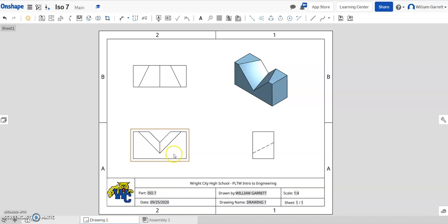So I could dimension a solid line on here. Like I could hit that bottom line, or I could hit this vertical line. If I want to, I can go point to point. I will point to line, so I'm going to start doing that. I clicked on my bottom point, and then I clicked on the point above it, at the point on my baseline, and I got a value of 1. I pull it to the side and between the objects, and I place my measurement. And then I'm going to continue dimensioning.